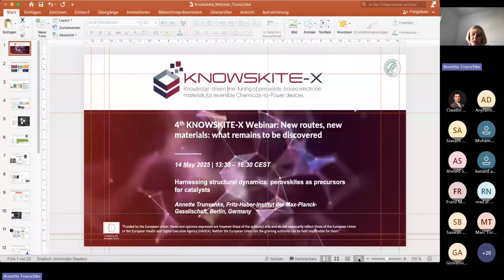So we form only 20% propylene and 80% of our reduction product is the undesired CO2. But if we add steam to this feed, we can substantially increase the selectivity. We form 50% propylene, which is quite good for this kind of selective oxidation. We can make with steam in the feed our unselective perovskite quite selective.